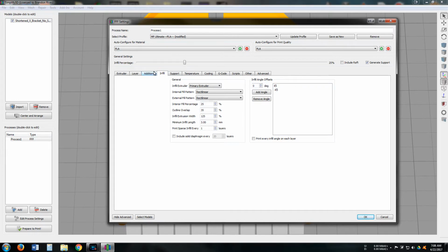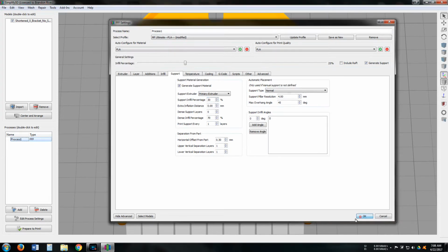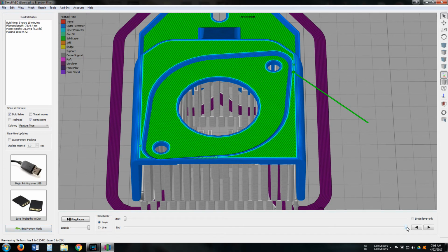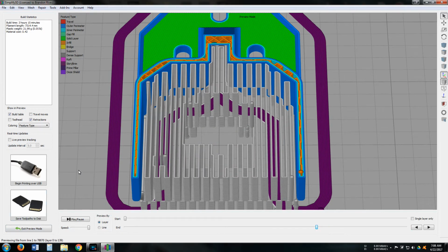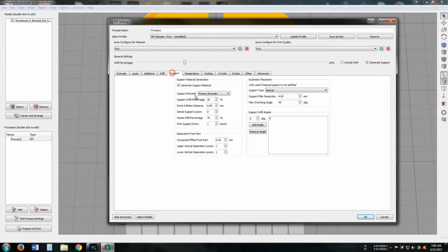But PLA can print with a smaller percentage of filament infill. So if you notice, it goes wider. So that's all we're going to do on supports. Let's go back and get through the rest of these settings. Those are really the only ones I use on supports. If you want your default one that comes up here, then you would change your settings to here. None of these other settings do I mess with other than this one and my default ones.